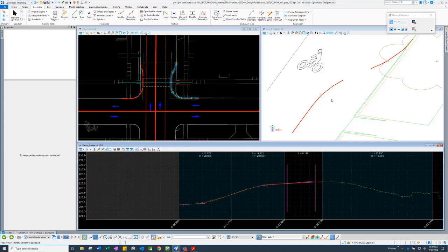You can do it during scoping, and that way, if you use control lines, you can just make adjustments as the needs change. So that's a great use of the control line idea. Yeah. They also filter into corridors. You can use control lines to control corridors as well. Absolutely. And use point controls to those as well.